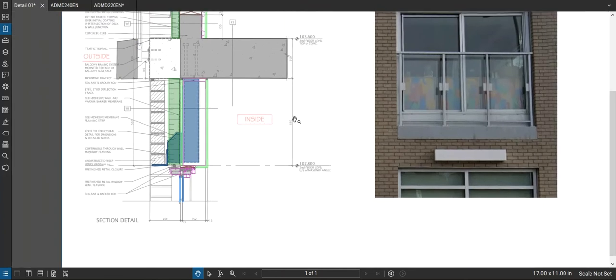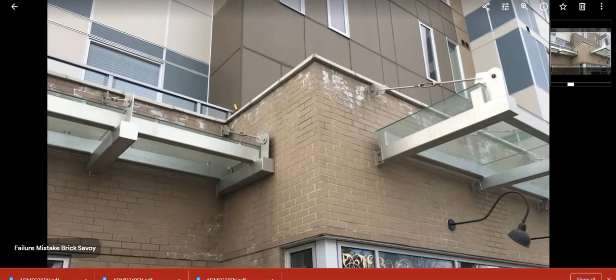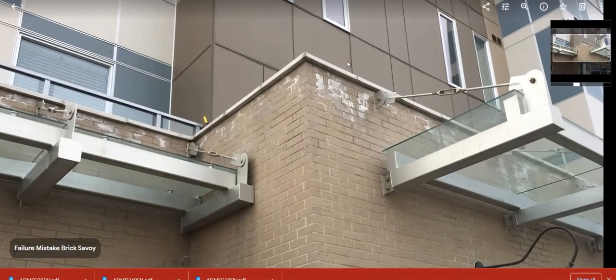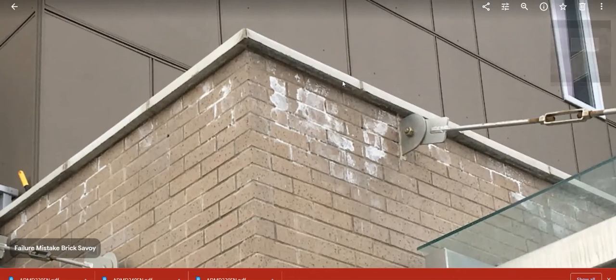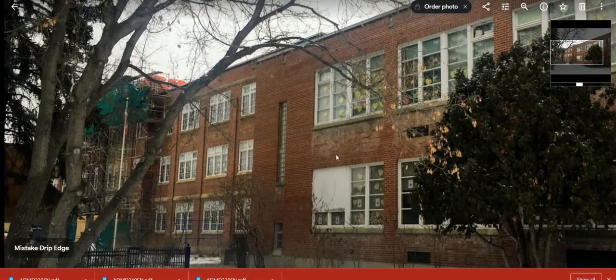and it'll bring some salts out from the mortar or from the concrete itself, or even from the bricks. And so here's a picture of efflorescence happening right here. So this concrete cap they put on here doesn't have a drip edge, and anyways, there's moisture happening here, too much moisture, and they're getting efflorescence happening. So it's the white stuff that you see on brick. And so here's another example of some staining right here.